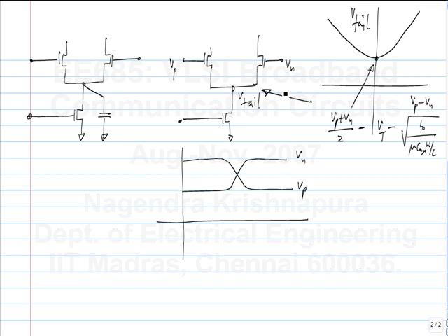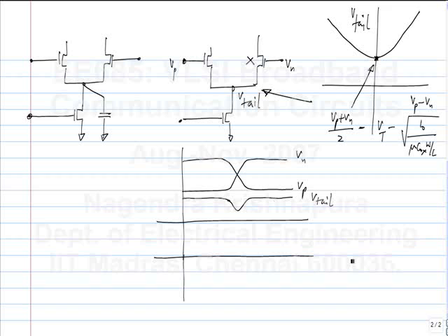So this is what it looks like, and if it is switched completely to one side, then if this is off, let's say, between Vp and Vtail it's a source follower, so it will keep increasing with Vp if one side is completely switched off. So it has its minimum value when Vp equals Vn. So Vtail may do something of this sort. Okay. So without capacitance, that's what it does.